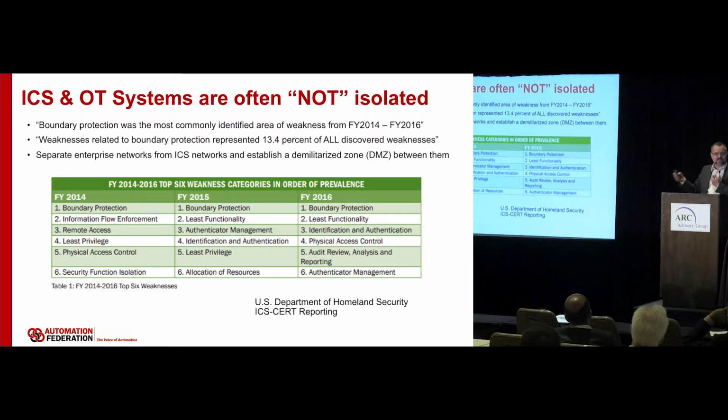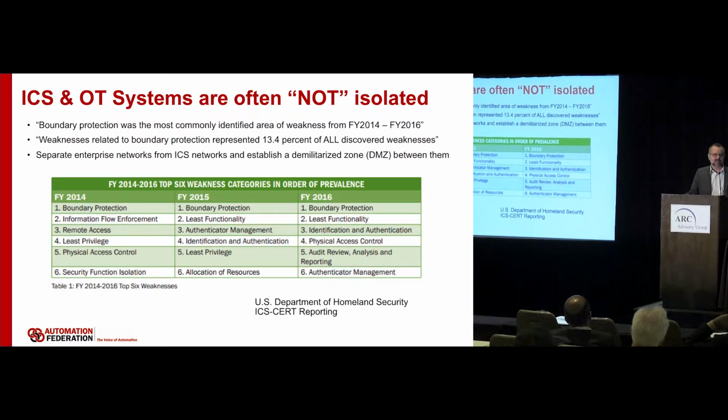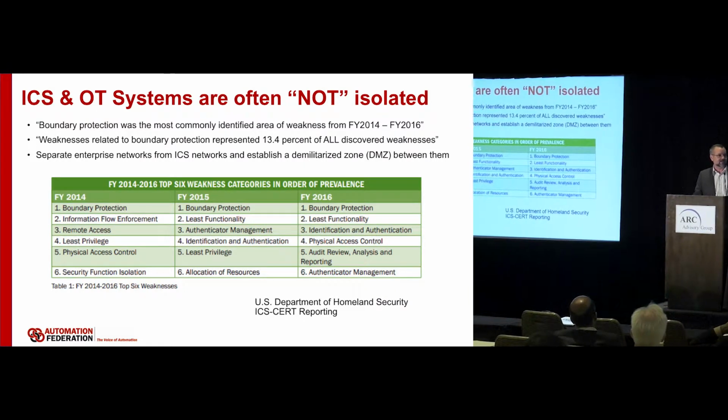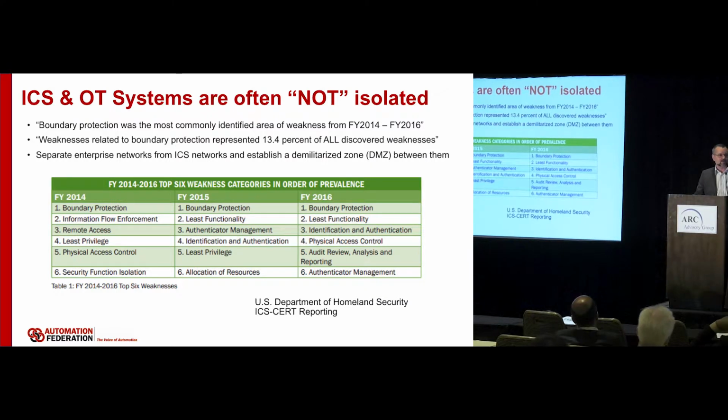So you could send messages out of the PLC by changing what logic you were running in it. Put a big block move in there which occupied more CPU space, and the fundamental frequencies of that changed. There was another one that was talking about varying the loads on big server power supplies so that you could see those loads go up and down, and then using that as a modulation technique. So there are many ways to get data out of systems that are essentially very well protected and isolated.